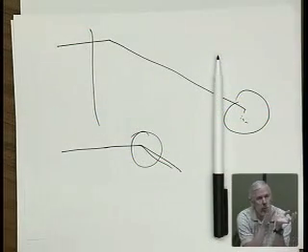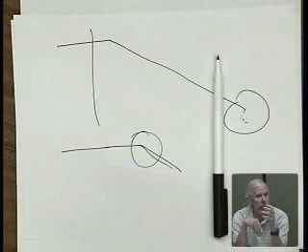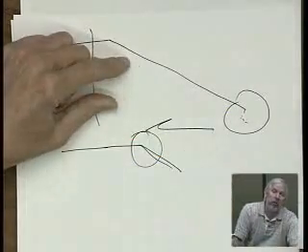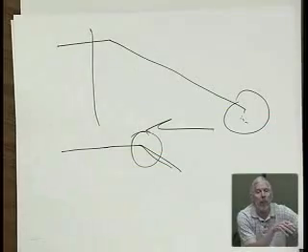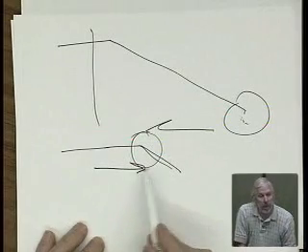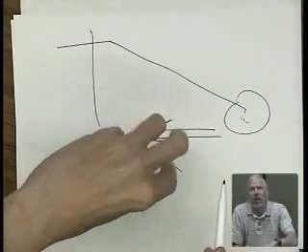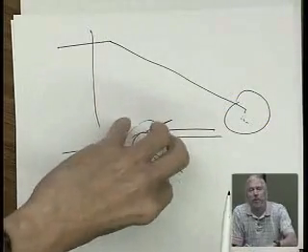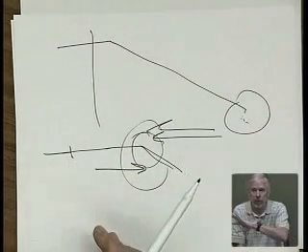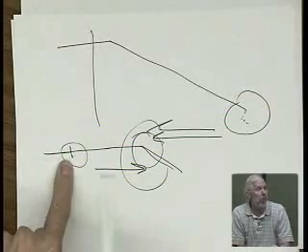You'll move it to a higher frequency by doing something like increasing the current that drives that node, reducing the resistance to it. Then what you'll no doubt find is another pole will start coming down to a lower frequency. Helping one will make another one worse. So you'll work on moving this one up, and then another one will start coming down. So you end up with a situation where you have everything sort of clumped together, which is the good design point. If one's really dominant all by itself, in the design you're doing now, not worrying about the stability issue, then you probably could have done something with that one pole that's all by itself.